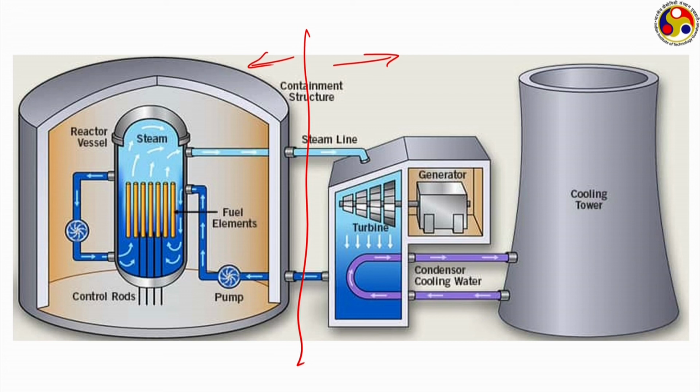Here is another point of interest to note: the control rods in the case of a boiling water reactor are mounted below, whereas in the case of PWR they are mounted from the top. As in the case of boiling water, the upper part of the vessel is covered only by the vapor phase. So there will be no point using control rods there; rather, it will be much easier to control the reaction if they are inserted from the bottom side.